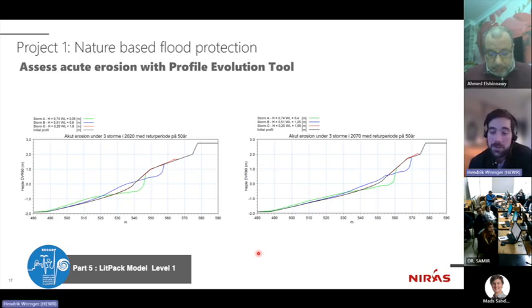So these events might have a significant impact on our coastline evolution, or are most of the storm events sort of small and just the position of the bars changes a little bit further away, a little bit closer, but overall the longshore transport will not be affected by that. And an additional component to that might be that this beach might in the future also be actively managed. So there might be some ongoing beach nourishment exercises, and then this assessment would be a component of that plan.